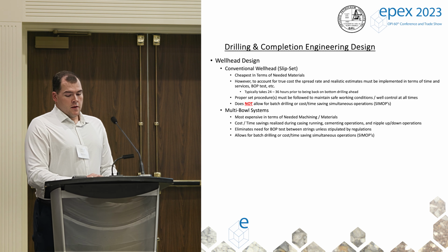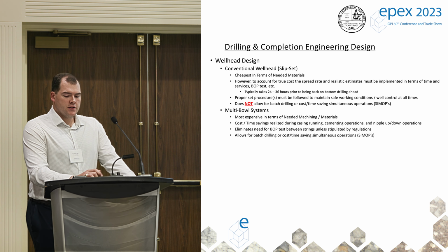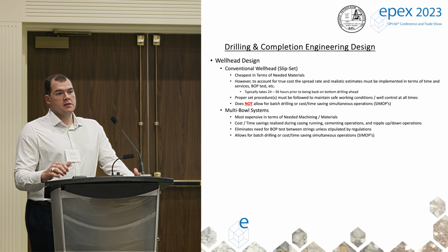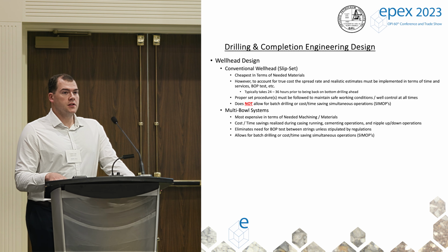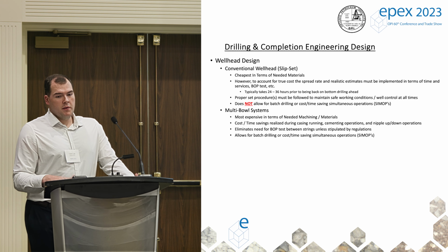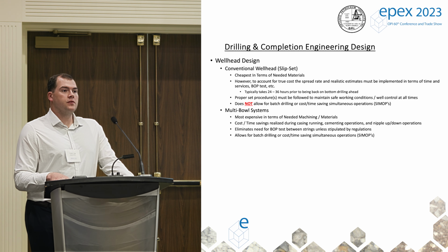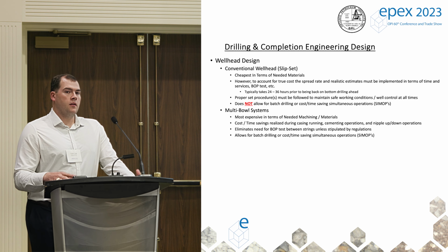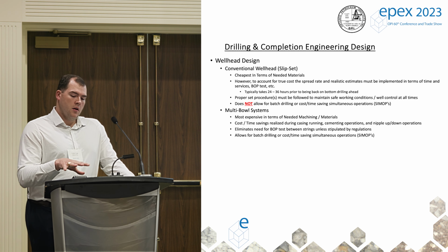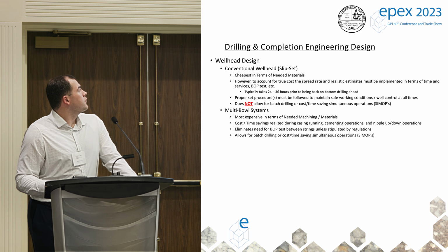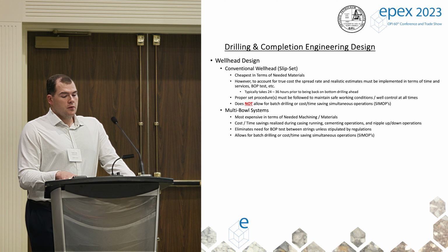Jumping into wellhead design, a lot of what we see, at least in the States, like I said, is historical production. So it was set with a conventional wellhead system where you're using slips and compression to activate those seals and provide your isolation. In certain parts of the country, especially certain parts of Texas where the salt is extremely shallow, you typically don't have enough weight to keep those activated and sealed in your system. What we see 90% of the time is they've got a bull plug in there, and they do not have an effective bradenhead monitoring program in place to track gas migration or fluids potentially into your base of usable water. So I would say, make sure you have the right tool for the right application.